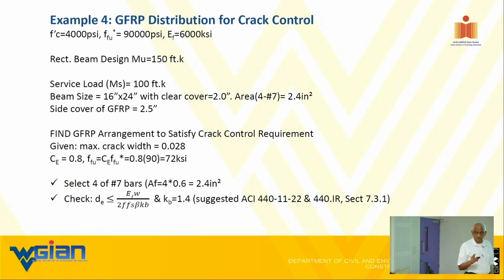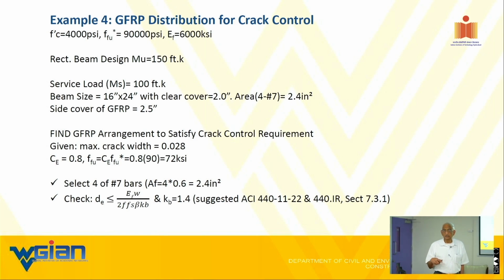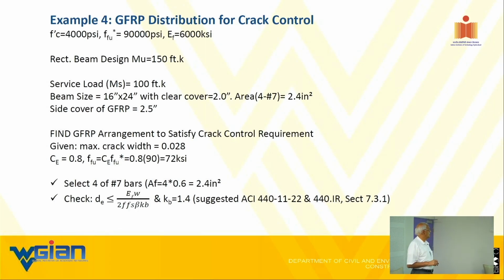When you talk of stringent quality control related issues, the reason we have such a small crack width limit state is because the de-icing chemicals go through and lead to corrosion, and that's what we're trying to minimize. And also we increase the cover from 1 inch to 1.5. Today our cover on the top is 2.5 inches. That's for bridges, not for buildings. Okay, so we can go through that.